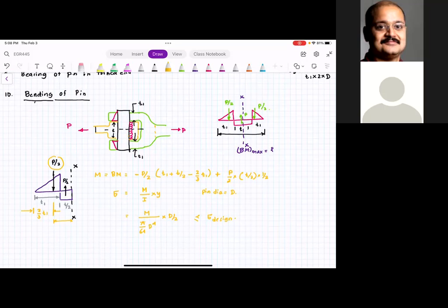So that's why in my homeworks, I asked you to perform the finite element analysis that will show you that if you look at the pin, the average stress in the pin would be same as what you calculated. But the stresses where the load is applied would be significantly higher than the average stresses. That is called the Saint-Venant's principle. So did you study that in mechanics of material? Okay. So what happens is,